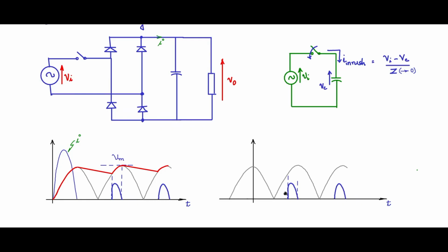The steady state portion, there is no change. It will be similar to what it was here. During this point, it is Vm, and it is Vm by impedance Z. The Vc is 0, that is, the charge on the capacitor is 0, therefore no voltage. So you will have a very large overshoot. I just want to show the relative magnitude will be something like that. It will be much higher than what would be for a synchronized switching where Vi starts from 0. So this could be a very large value. It could go to thousands of